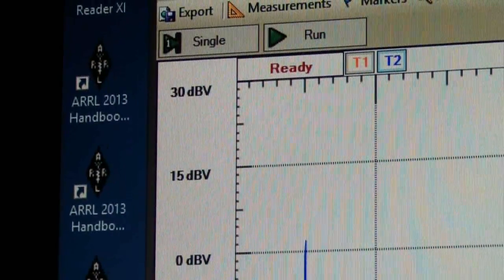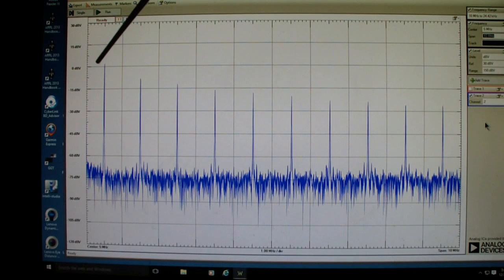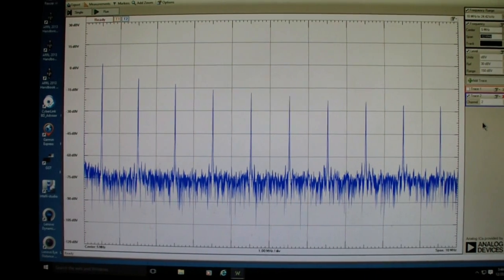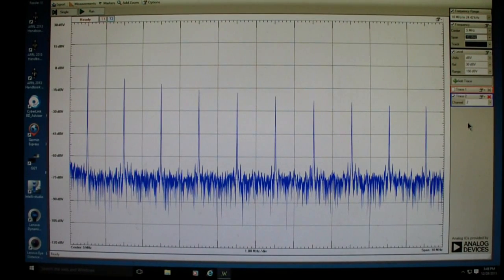dB volts. The analog discovery has an upper limit of 10 megahertz. And so one of the reasons that the early demonstrations here have been at 500 kilohertz or the frequencies in that area is that you can't really, if you look at this display, given that this is 1 megahertz and this is 10 over here, that's the frequency limit of the analog discovery.